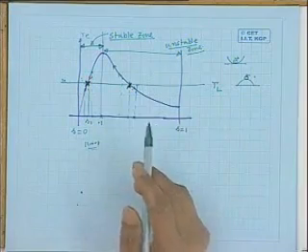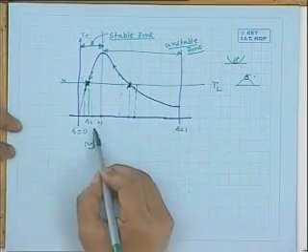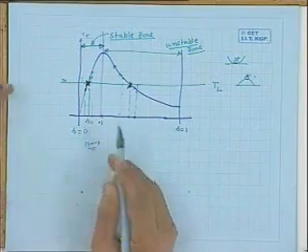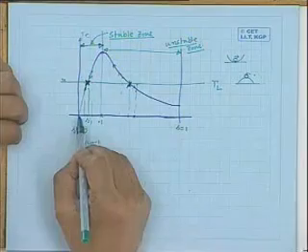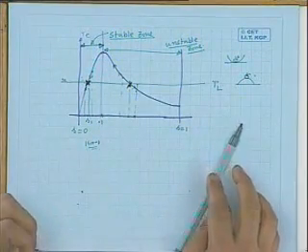That is, for a typical machine, if this is 0.1, you can say between slip 0 to 0.1, stable operation of the induction motor takes place, and between slip 0.1 to 1, unstable operation. Of course, this 0.1 is no unique term, as I told you. It could be 12%, 13%, like that. Okay. So it is this thing one should be careful about.